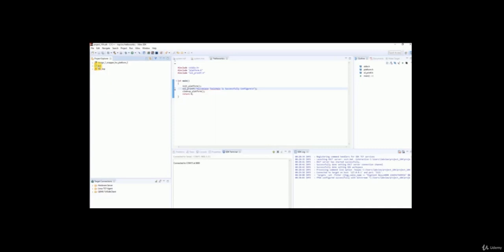Once you see the message connected to COM port 15 at the specific baud rate, you can be sure that your console is working fine. Now we'll select the top folder where we have our helloworld.c, right click, Run As, and then Launch on Hardware. Inside the SDK terminal, we are able to see the string that we added inside xil_printf. This suggests that the entire tool chain is properly working, and we can go ahead and consider the complex scenario with a MicroBlaze.